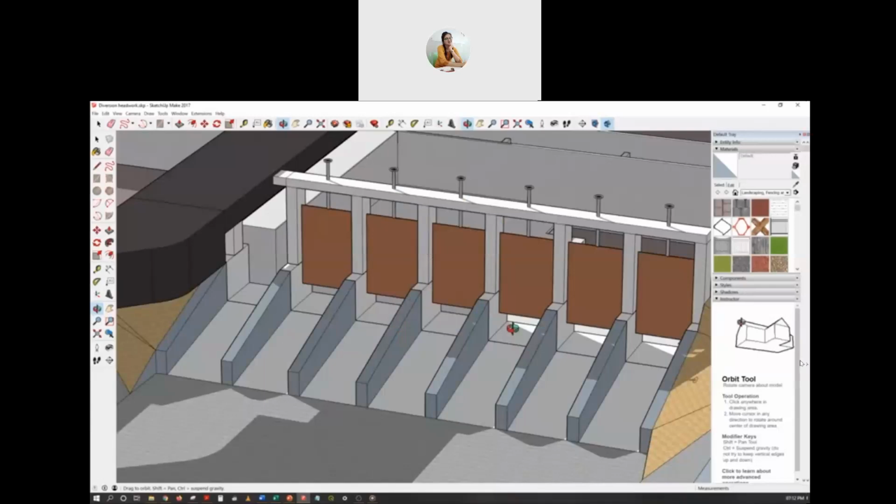Now, this part, these tunnels, are called silt excluders. What they do is, when water flows to this location, the silt carried by the water will be mostly carried near the lower part of the flow. So that part enters these tunnels. If you see, those tunnels lead to the downstream. There are some more gates here, here, here.